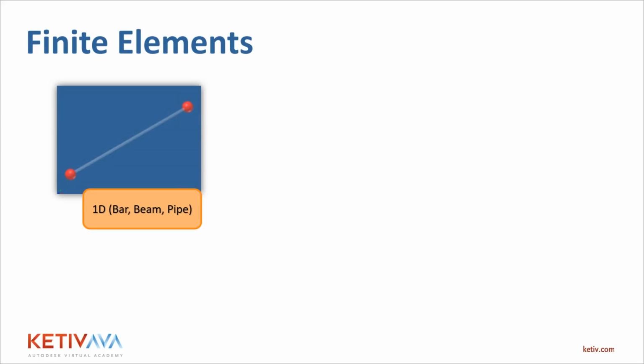Now, to define the geometry or cross section for a beam element is going to require several cross sectional properties. Now, to input this data, you can either put that in from empirical data, or what's recommended is that you use the inbuilt element library, which has a lot of preset standard sizes that you can just pick, and it's going to populate every property that you need for you.